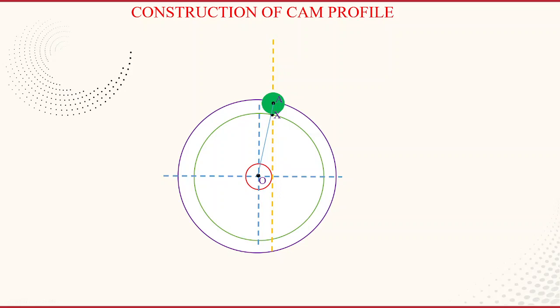Now outstroke is 80 degrees. Just mark from this reference line OA to the 80 degrees, that is acting as the outstroke, and divide this outstroke into 8 equal parts, and assign the numbers and draw the lines which are passing through these points and tangent to the offset circle. See that? Okay. Now again you take this O8 as a reference and measure the other angles.